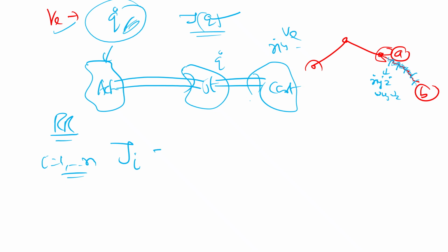So what is the formula? Actually, we have two kinds of joint, the revolute joint and the prismatic joint. So if it is a prismatic joint, then the Jacobian will be the position vector of i minus 1, 0. Okay, so this is my Ji for the prismatic joint.